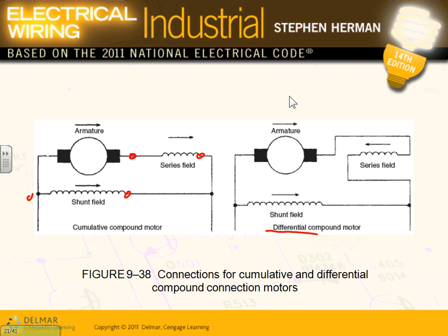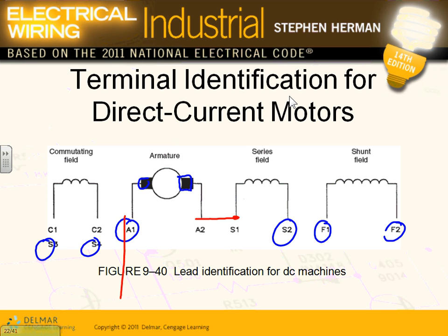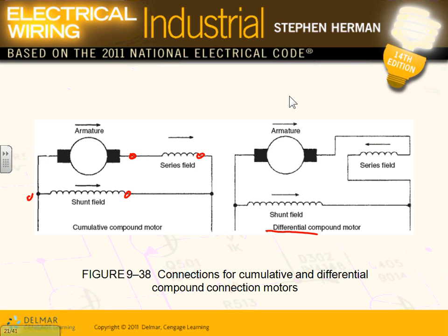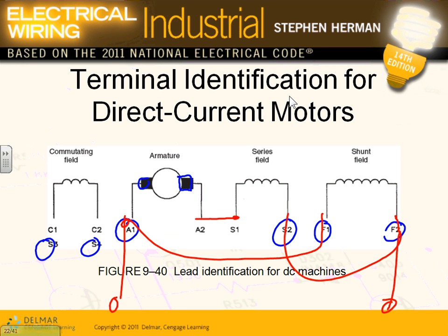Let's do the shunt cumulative. So, where's my shunt here? You grab this one, you tie it here, and you grab this one, you tie it right here, and then you bring the voltage from these two sides. So that's why they give you the whole wiring methods for these. This is one wiring method for that baby. It's shunt across both of them. So I grabbed that one and shunted it across both of them.